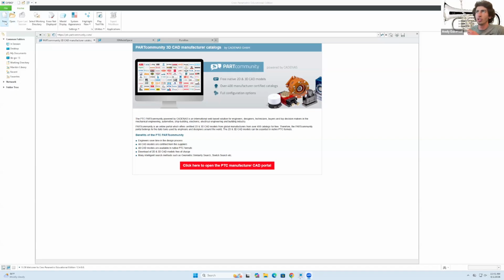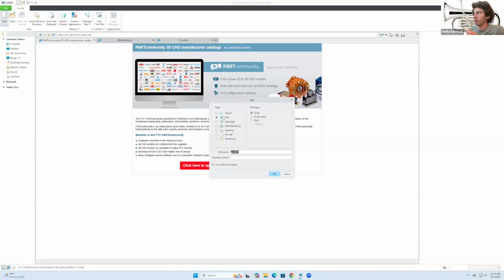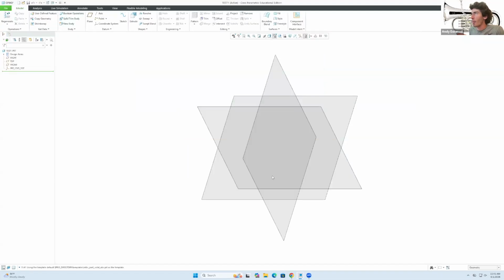You go here to where it says New, and I'm going to select where it says Part. And when it prompts me for a name, I'm going to say test one. You can leave this as use default template. If there are things that you want to change, you can change them later, as I'm going to show in just a minute. But I'll click on that, for example, and I'll click on OK. So now it's going to take me over to the main Creo interface.